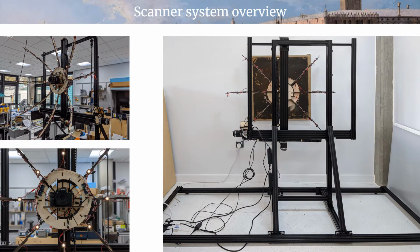The prototype scanner is designed to capture the color and structure of planar surfaces. The design offers an affordable and simple solution to acquire image data. The cost for all the materials was just under £1,200, excluding the camera. The system uses a digital camera. In this case, we used the Sony Alpha A7R Mark II with a Sony 50mm lens. The camera is coupled to LED screw linear actuators placed perpendicularly on a 1 meter by 1 meter extruded aluminum frame. The system allows the recording of all necessary image sets automatically and seamlessly, reducing the capture time.